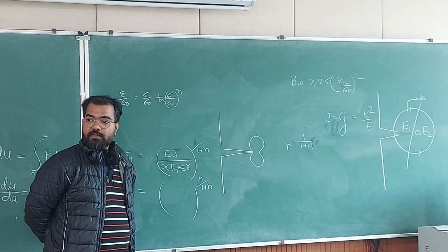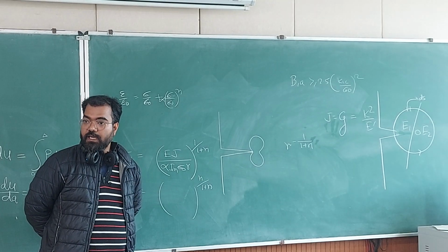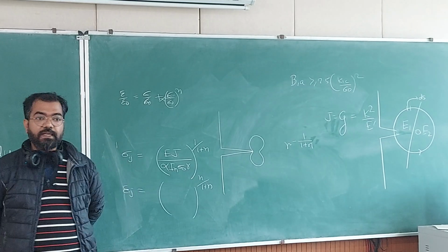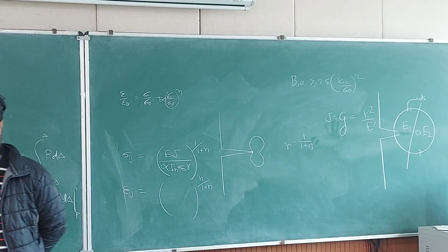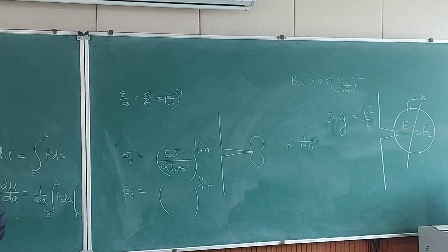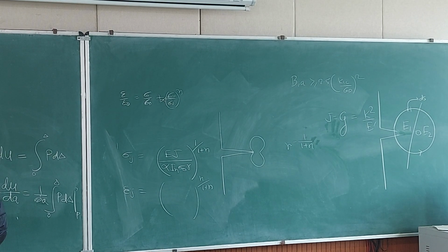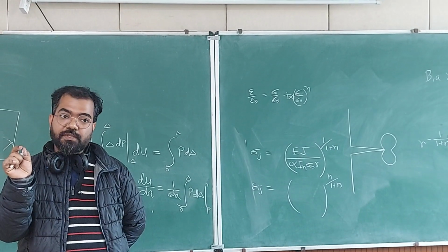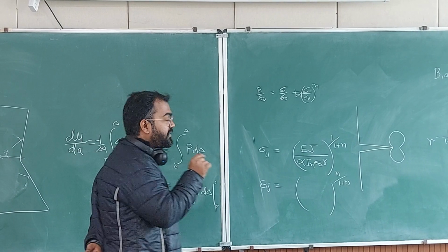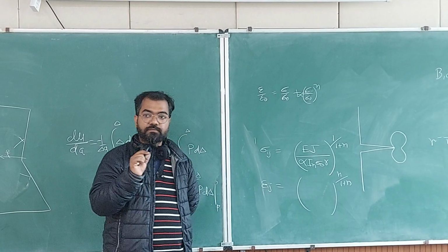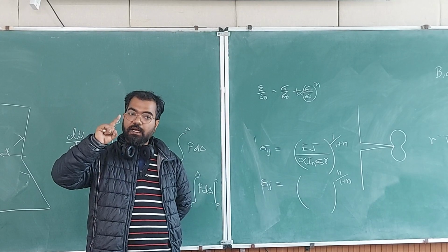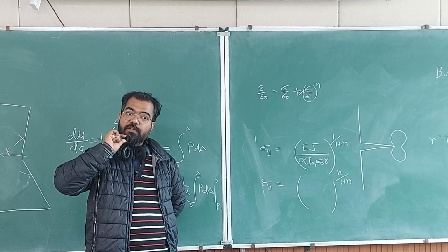It is the same thing like Irwin's K formulation. Right? But K could not go inside the plastic region. This can go inside the plastic region. So the r can be very small, but still cannot be 0. Okay? It still cannot reach 0. So this is also defining a singularity. You have a singularity, so you have an asymptotic curve again for a very small value of r.